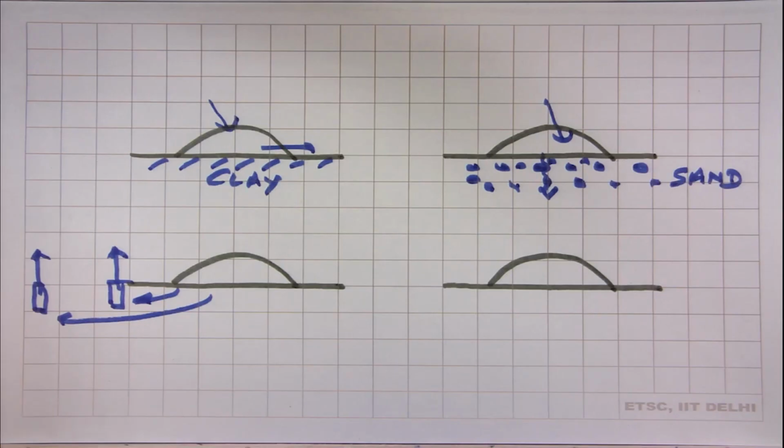If they have fractures, joints, fissures, are they pervious or impervious? Are they more pervious than clay? Yes. Are they more pervious than sand? Depends on the size of the fractures, but some of them can have very large sized fractures.